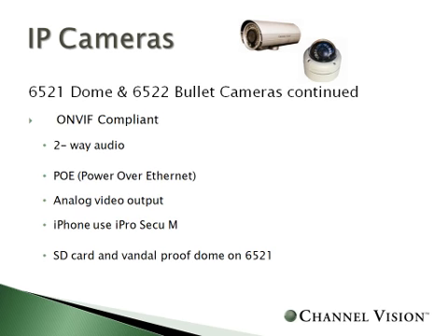Some additional settings that you'll find in these cameras are ONVIF compliance. We touched briefly on ONVIF, implying that this is a universal standard in the IP video world, implying that everybody will be able to play nice together as long as you carry an ONVIF certification. In addition, the IP cameras, both options, offer two-way audio, power over Ethernet capabilities, as well as having an analog video output, which is a unique feature to the Channel Vision cameras.